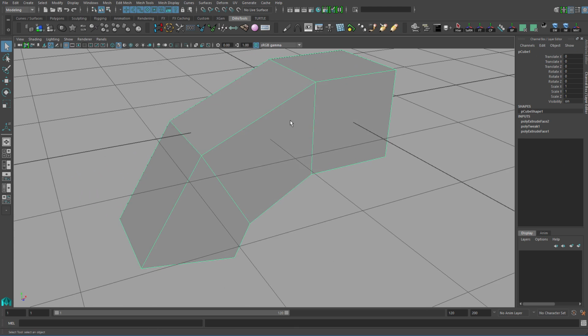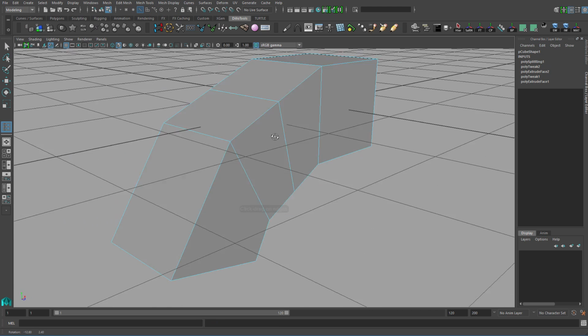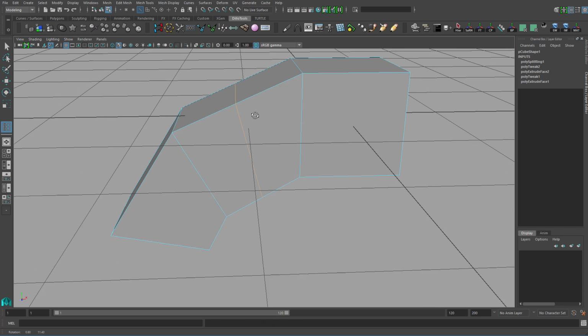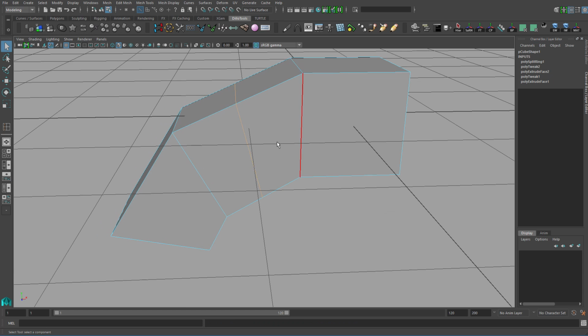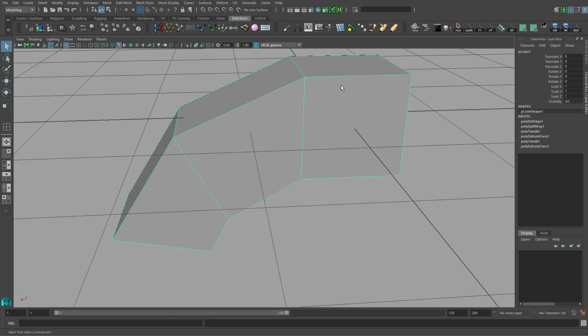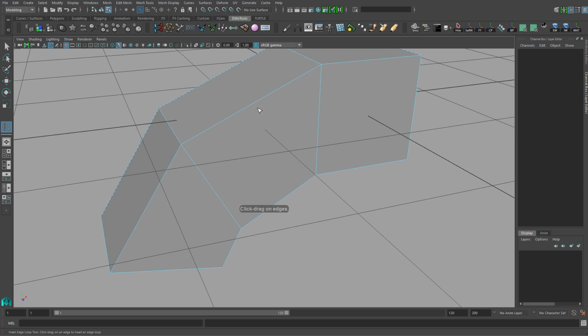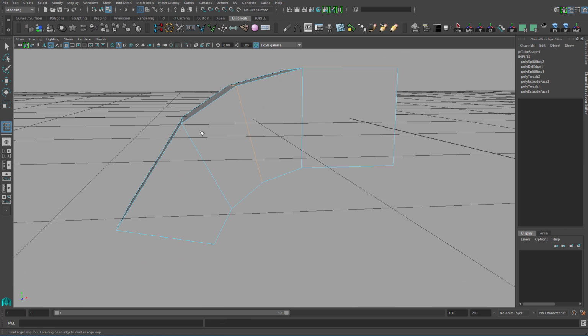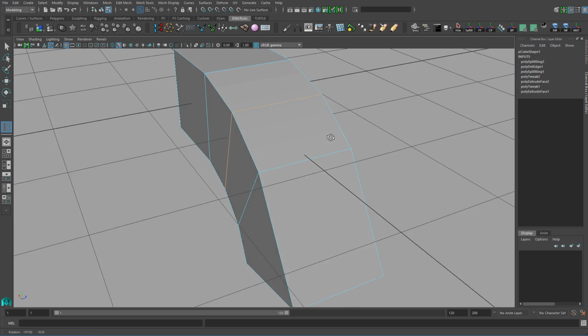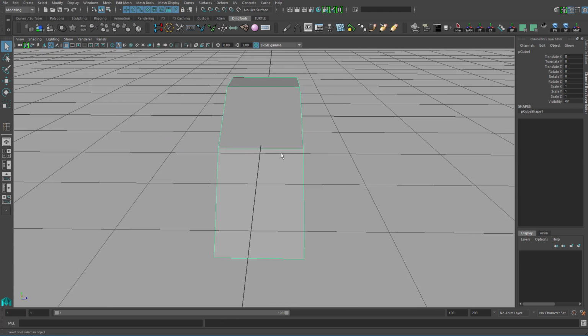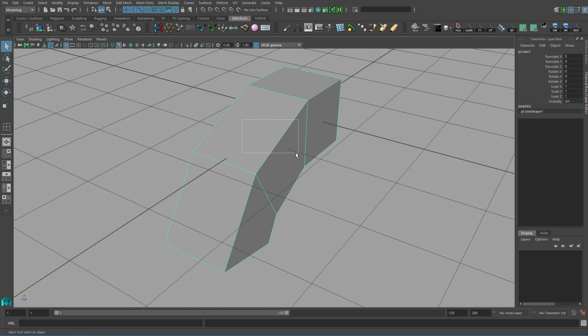And then I want to add an edge loop here. But in the default settings, this edge loop kind of tightens its curve up, so it becomes not that smooth anymore. So instead of doing it this way, when you're using the Insert Edge Loop tool, holding down Shift and click and drag on the edge, that can actually try to match the curvature for you. Okay, a very useful technique. So that's Insert Edge Loop.